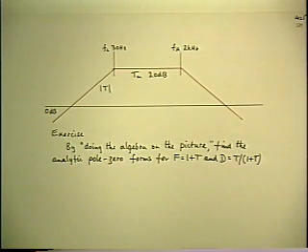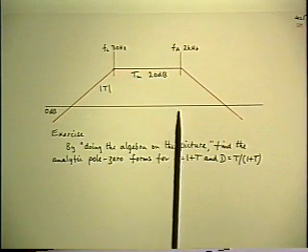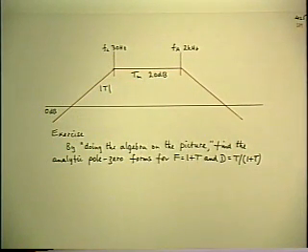And so this requires the graphical construction that we've been talking about, and this is a little extension of the one we already did as the initial example, and so I'd like to leave you a few minutes now to do this. That is to construct on this graph, which is the T we have already, construct graphically the F, which is 1 plus T, and write the result in factored pole zero form. That means that you get the analytic form for the result, the quantitative result, but you do no algebra directly. Instead, you effectively do the algebra on the graph. So I'll leave you a few minutes to do that.